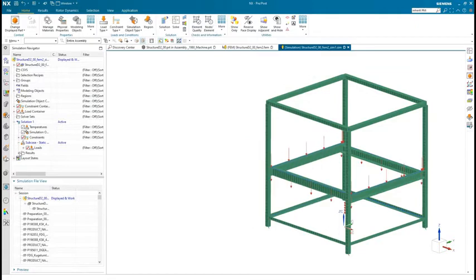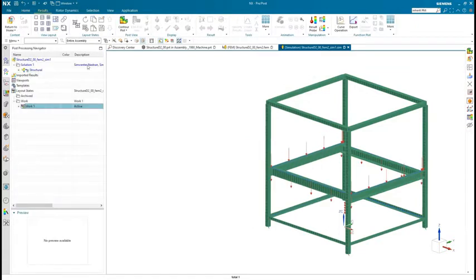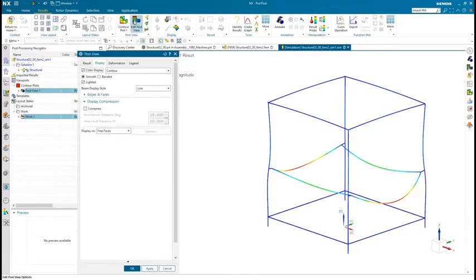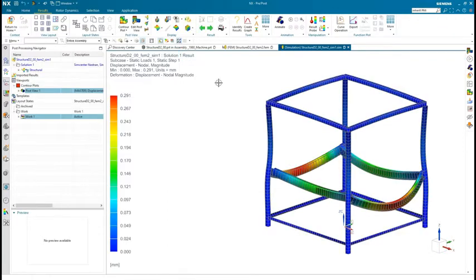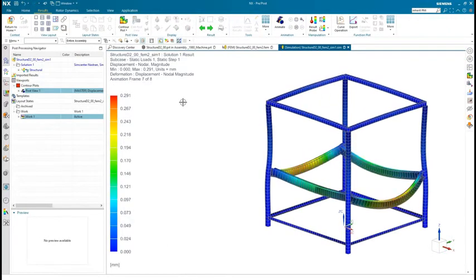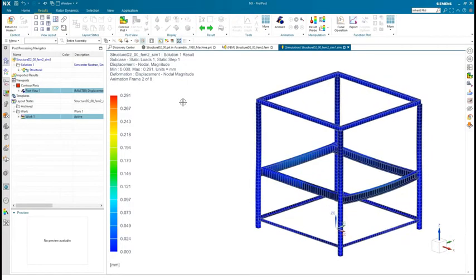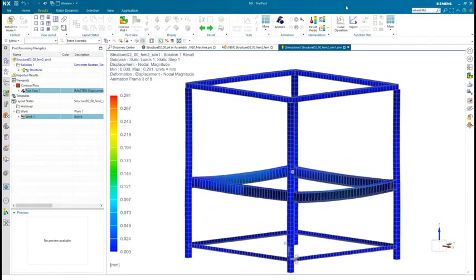Again, since our design is based on beam-type shapes, beam elements are used for the mesh, which tend to solve very quickly. Here, the entire model solves in just a few seconds. As we review and animate the results, the total deflection is slightly higher. This amount is still within our design parameters, but now the machine can be assembled easier.